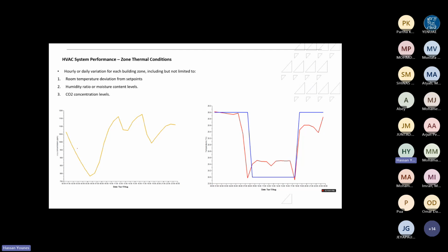Look at the performance in terms of CO2 concentration. If you find that the CO2 is always 400 inside the building, that does not make a lot of sense. If it's modulating based on occupancy, that makes sense then. And again, if you find something like 10,000 ppm in the room, maybe you put too many people in there. So figure out what's wrong.